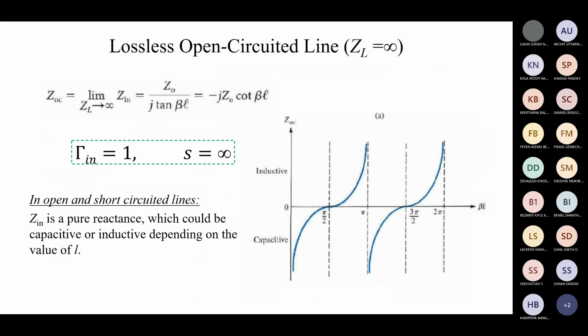And what about an open circuited line? The open circuited line is nothing but we have a source and there is a transmission line. This is completely open, nothing else is connected. The positive and negative are not yet connected to anything. In that case, we can call it infinite impedance. That is why no signal is going away. In this case also, whatever signal is coming will be reflected back.